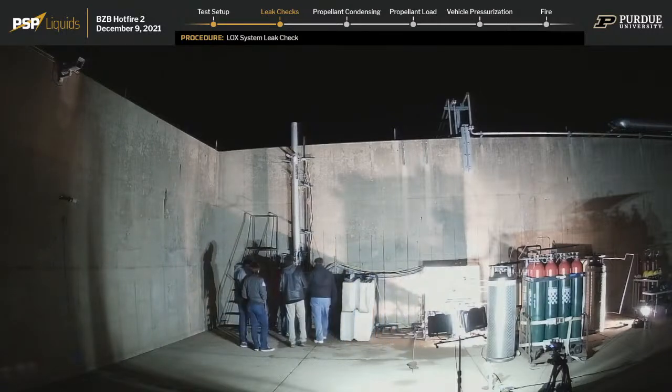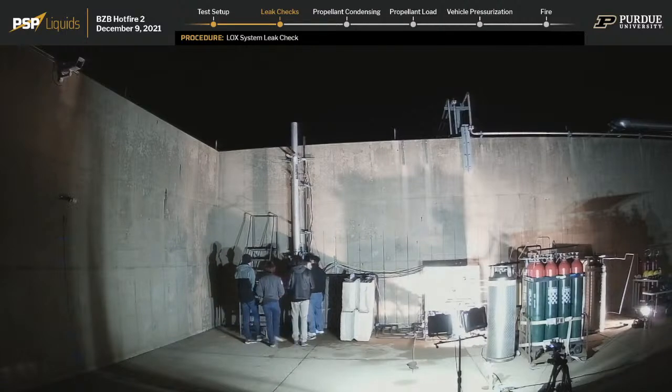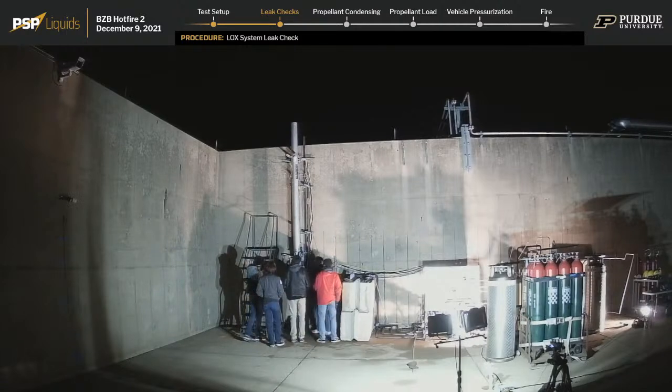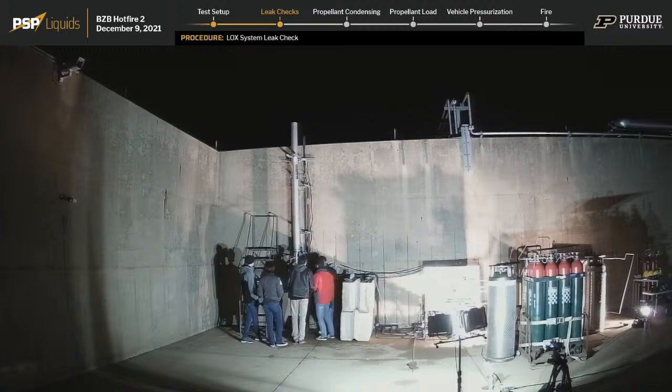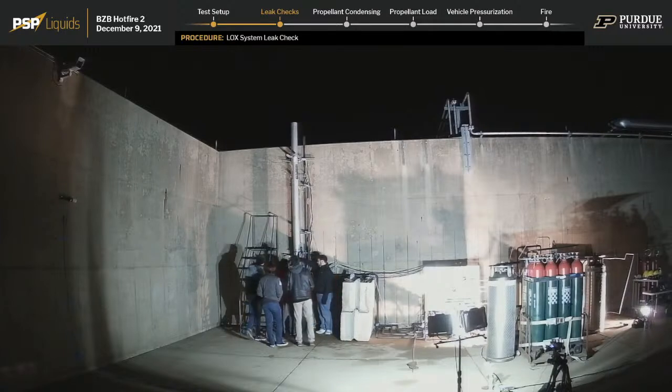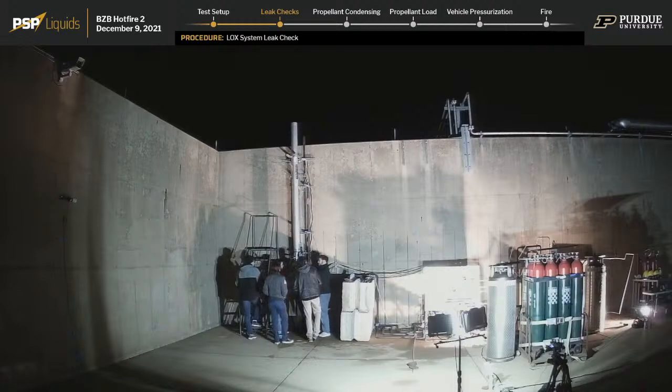give us things like expected trajectory bubbles, as well as safety zones. So if we go on a ballistic trajectory, what would happen to the rocket, and how much distance around us do we need? We also, as soon as we're done with tonight, can plug the thrust data into our 1 degree of freedom, 3 degree of freedom, and 6 degree of freedom models, and that will allow us to get an expected altitude given performance. That's right, Aiden. And this Hotfire test serves really as a full validation of our system, so we can figure out what we need to improve before we actually fly this vehicle.